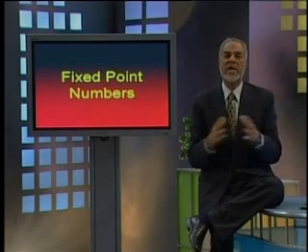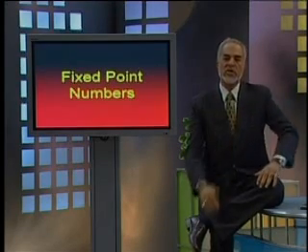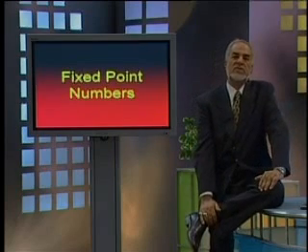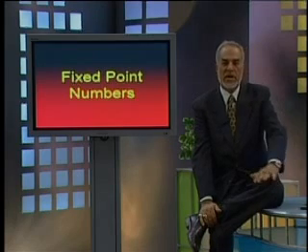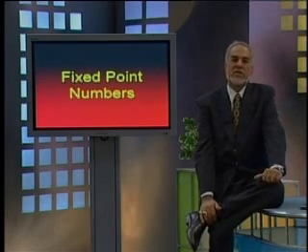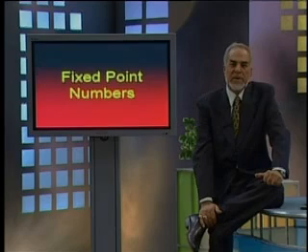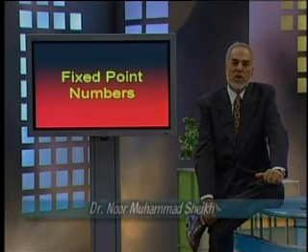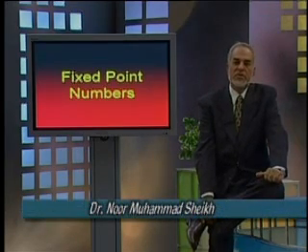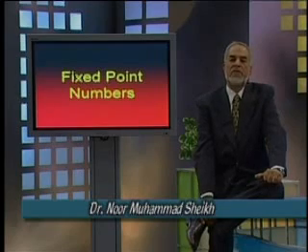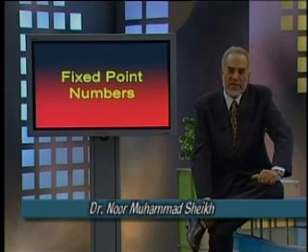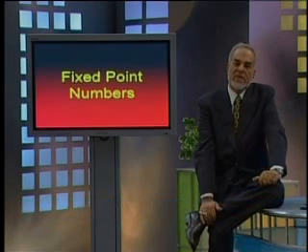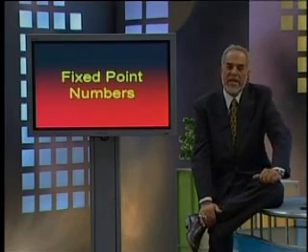So this would be a scaling operation, and you remember in one of the SRC operations, when we shift arithmetic shift left or right, we implemented an algorithm for multiplication with a power of 2 or division by a power of 2. It could be division, but in SRC, in Falcon, we had these multiply and divide instructions. It was not there in the SRC processor.